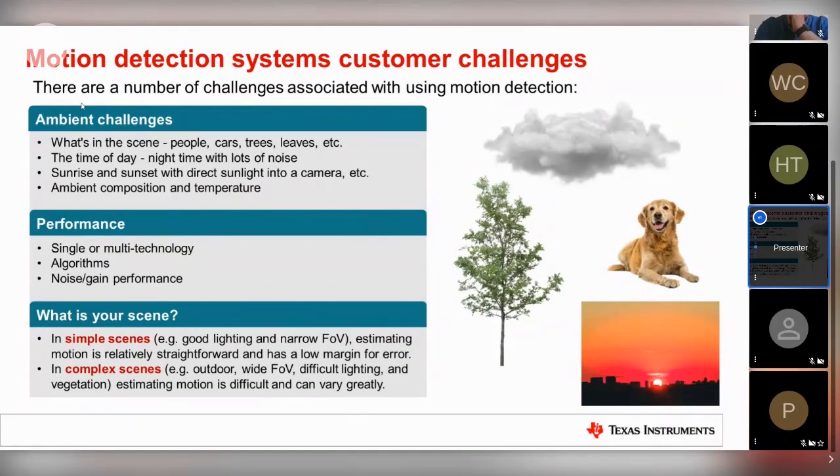Naturally, there are some special technology that we can implement, like a lock-in amplifier that can extract the signal out of the noise. So if the signal is maybe 10 times or 100 times smaller than the noise, we can still be able to extract that one using a different technology.